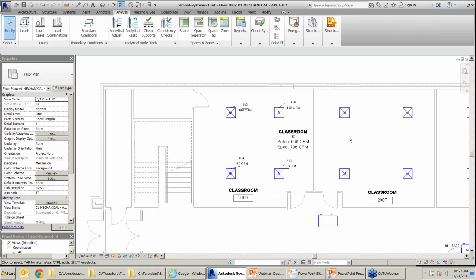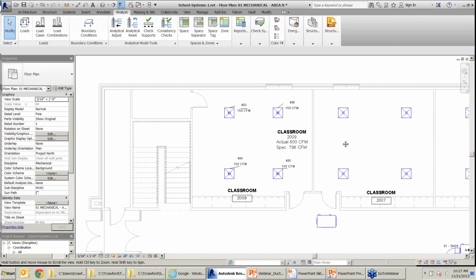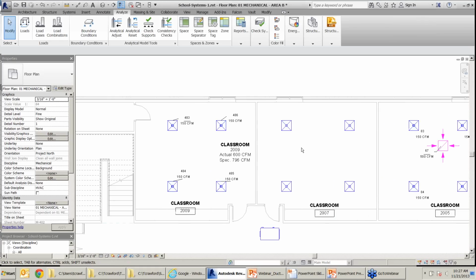Say a giant entryway where you know there's going to be 2 different areas. I thought you could say this area was a seating area, will have this much CFM. So can't you create some kind of a mocked up area that you can base off of space? You can put in artificial space boundary lines. So wouldn't that work if he's not being able to do that? Can he just make an artificial boundary line and then try it again?